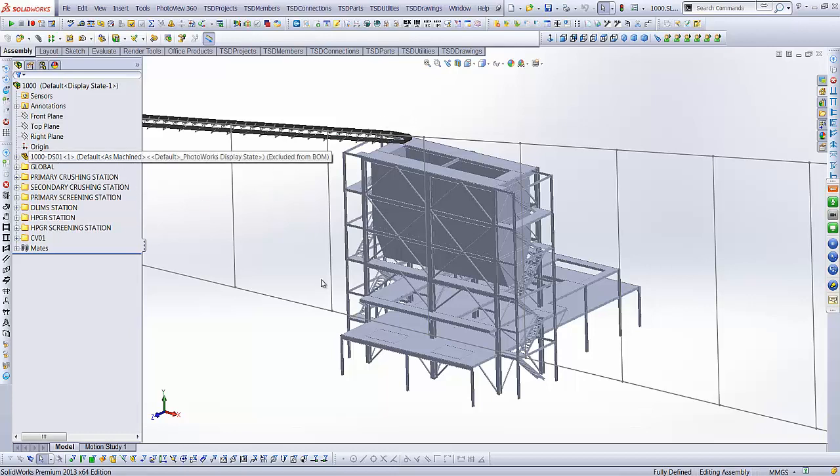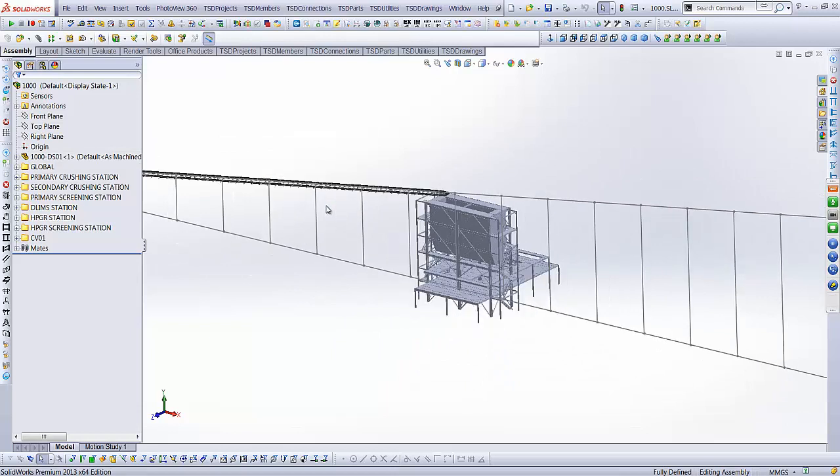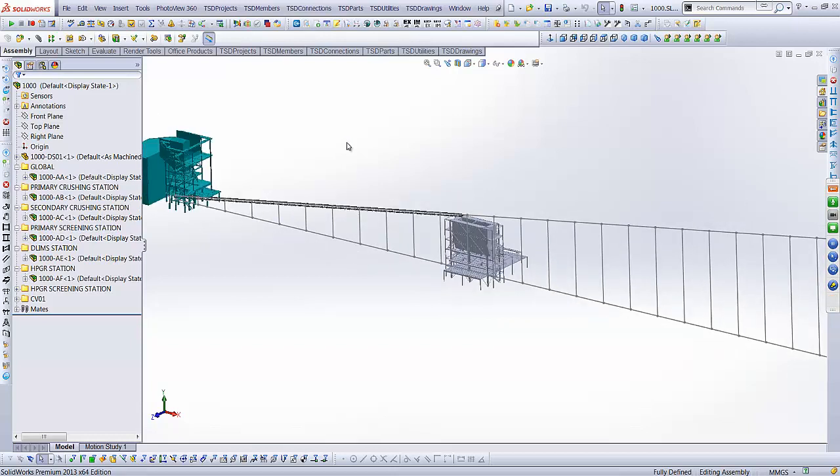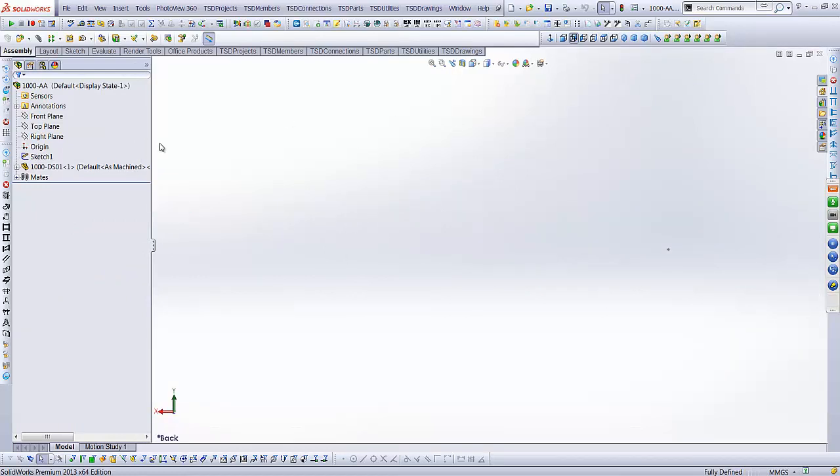So I'm just going to get into the driving sketch that you can see here. Okay, so this is what we call a top level project assembly. If you attended last week's webinar, you would have seen a project top level assembly, and you would have seen how that's been created based on different areas. So the last project we did cover was just one area. In this case there are several areas, and in each area we have the driving sketch, including in the top level. So it means that if there's a project lead looking after this project, he can actually go in and change this to suit, and the others will drive. So if I go into a lower level assembly, which is where everyone will work, there is a driving sketch.